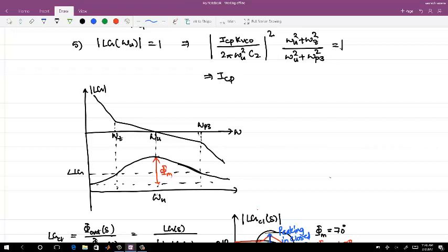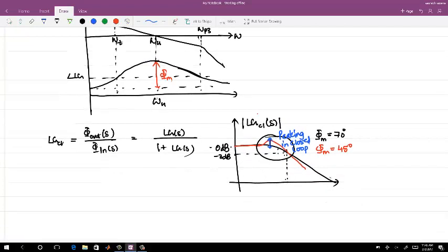Let's say the reference noise is white noise, and the charge pump noise is again white noise. All the white noise sources closer to the input, we will see that in detail, will get amplified with the peaking. Whether they are amplified more or less, that's again a study. So that is with regard to the phase margin.